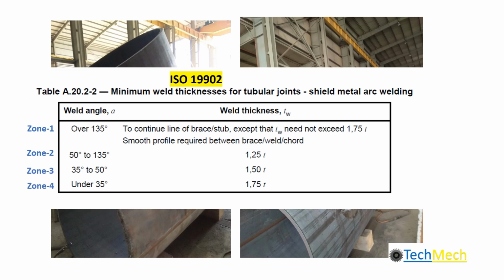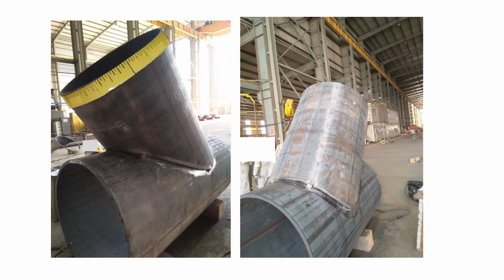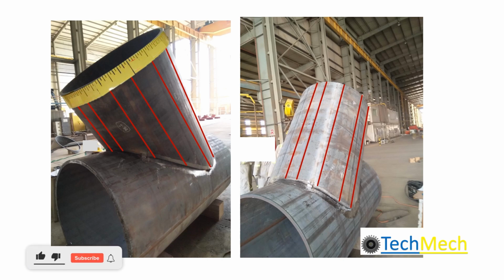The first method involves physically checking the local dihedral angle at the desired point to find out the zone per local dihedral angle range. First measure the outside circumference of the stub. Divide the measured circumference into equal parts as deemed necessary. This totally depends on your estimation. It can be judged whether 8, 12 or even more or fewer divisions are required. I normally divide the circumference into 8 equal parts.